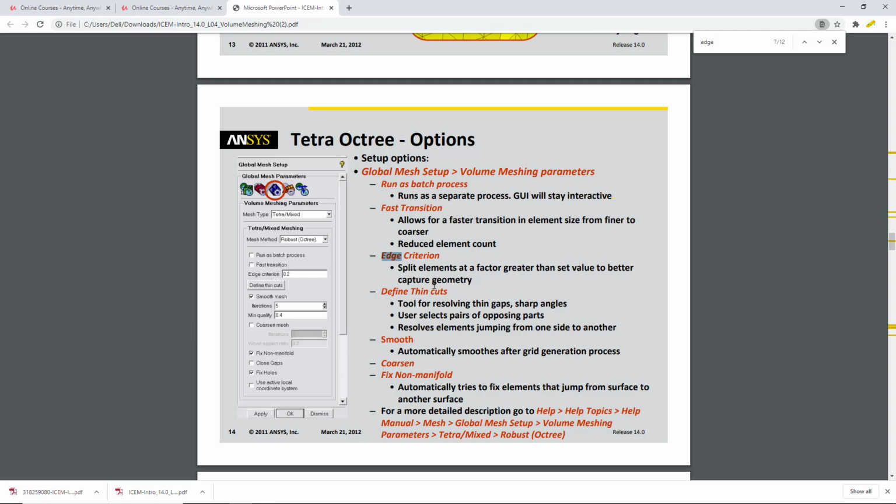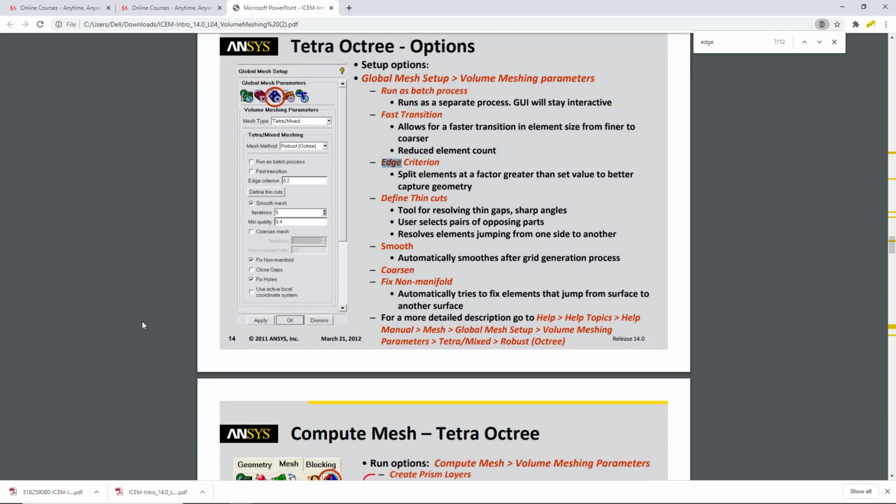So definitely this is a problem we are getting, and this is the main issue from where I started to look for the solution. And then I came up with many things in the model. These are the geometry capturing. Geometry was not good at some boundaries, so I just recreated geometry from curves. And then I defined the sizes on the different parts and the maximum element seed size in the volume. The next thing is the H criterion.